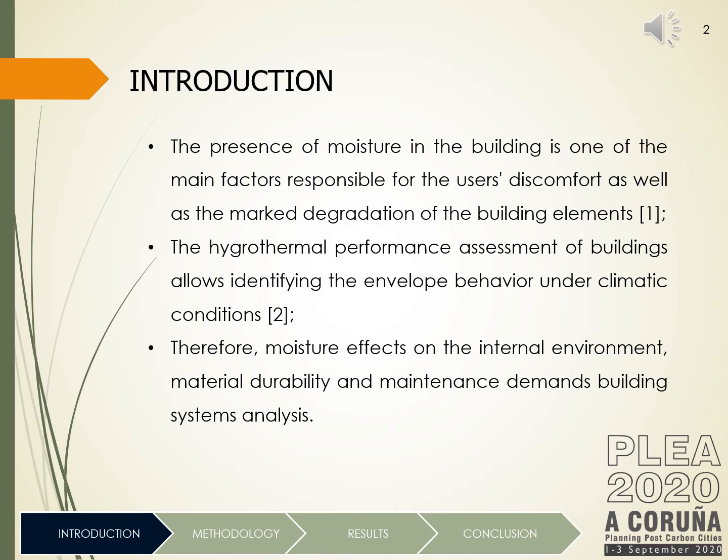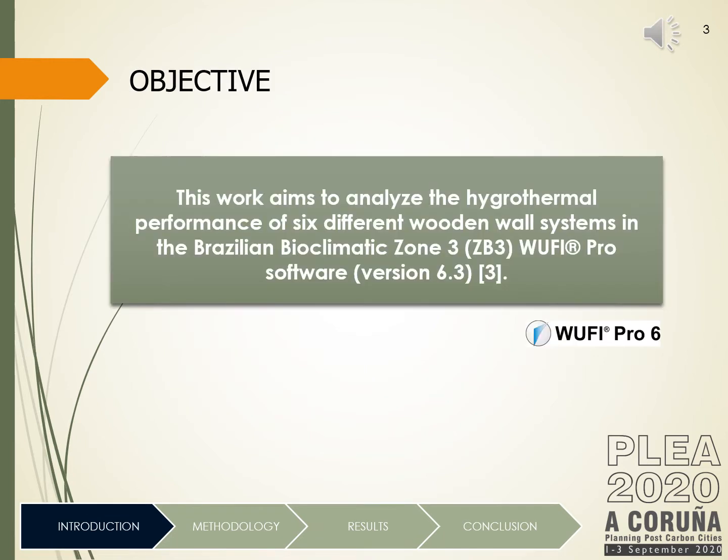Thus, it is of utmost importance to analyze the hygrothermal behavior of the building's materials and building system considering the weather conditions to which they are exposed, to predict their durability and internal environment quality. So, this work aims to analyze the hygrothermal performance of 6 different wood wall systems in Brazilian Bioclimate Zone 3 with WUFI software version 6.3 to identify the moisture flows and the thermal performance in a building located in that ZB3 in Brazil.